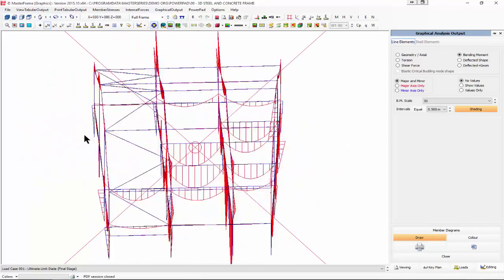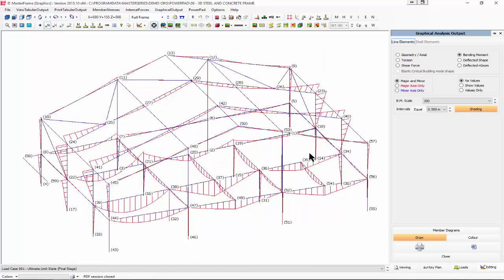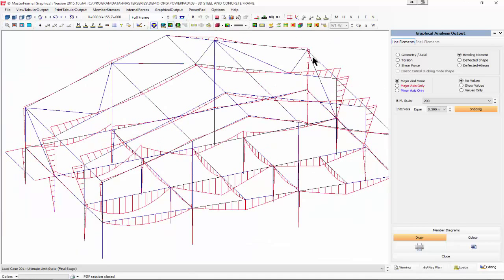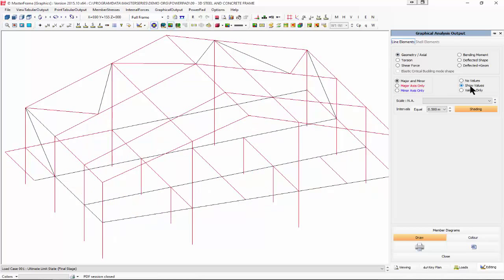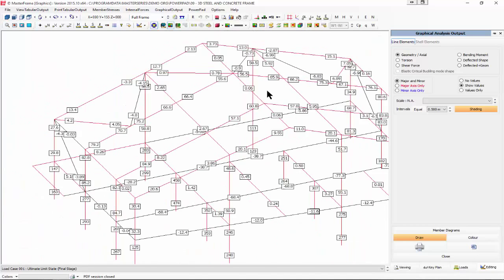So obviously you don't look at those with the 3D. We can see all the beams coming through, and we can see in here, if we just reduce the scale and take off the node points, we don't need those, the primary beams and then the secondary beams that are supported. The fixity that's coming through in this case, because somebody was playing around, means we're getting a little moment in the columns there. We see the major moment in those, but the minor and the externals, because we aren't taking those to have no axial, they are taking propping action. And if we wanted to check that one out, we can ask it to show me the values and see the propping action of 58 kilonewtons coming through onto those columns and back out again.